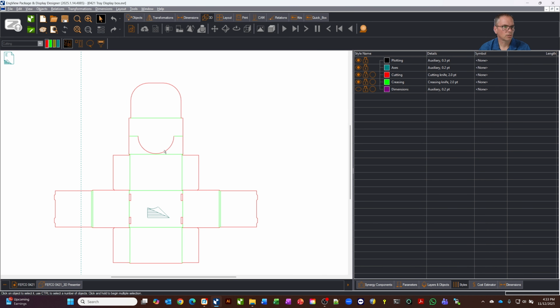All right, so let's say we want this to be perforating. I'm going to hold my Shift key and my Control key on the PC. It's slightly different on the Mac. I think it's Command and something. And I'm going to click on that one line. So that one line is now highlighted. I'm going to come over here to my perforating tab, click on perforation, and do my 1-inch cuts. Okay, so now you can see that this is my perforating style and I can turn it on and off, and that's got a new style.